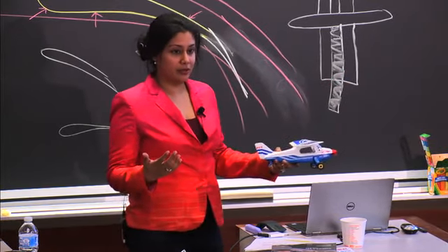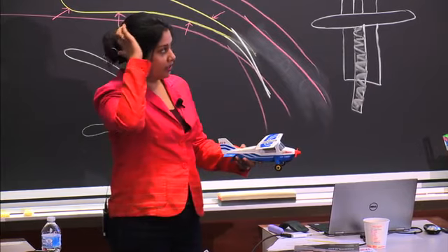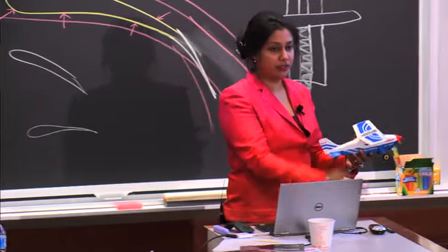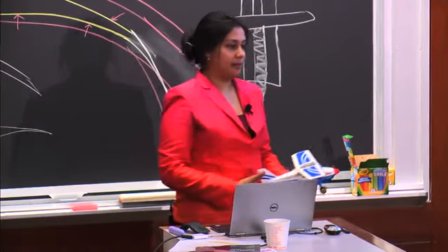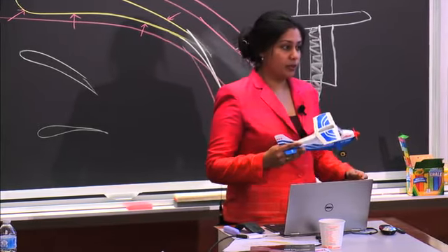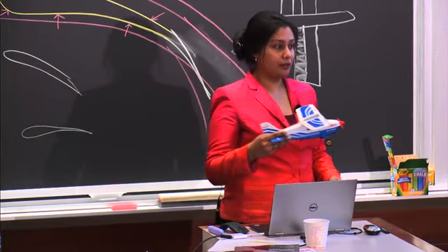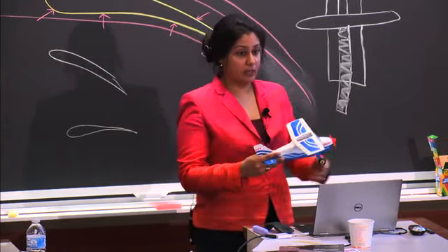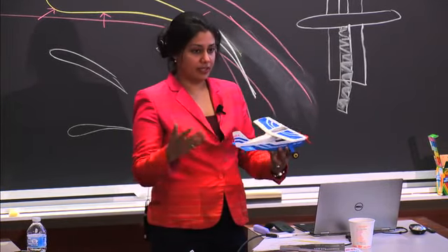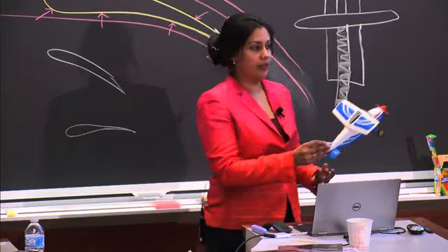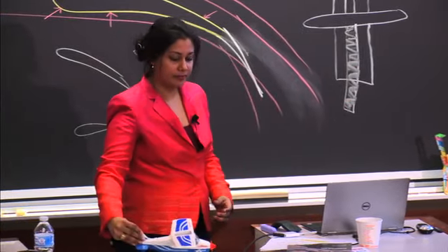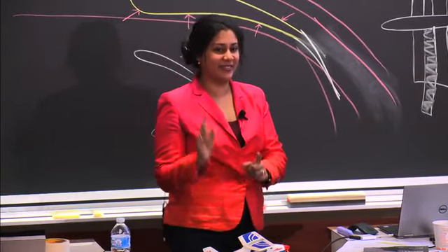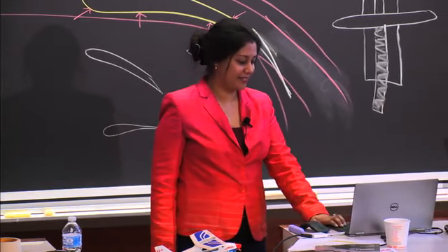Well, you won't be able to sustain flight. And so this is why ground effect is really important: you can float over the ground because you're so close to the ground that the ground is blocking some of the effects of the air. So what you want to do is make sure that you continue your ground roll, even if you're a little bit airborne, and stay close to the ground until your airspeed comes up to that rotate speed, in this case 55 knots, and then you pull back on your yoke to take off. So when does ground effect happen? When you're close to the ground, within one wingspan of the ground.